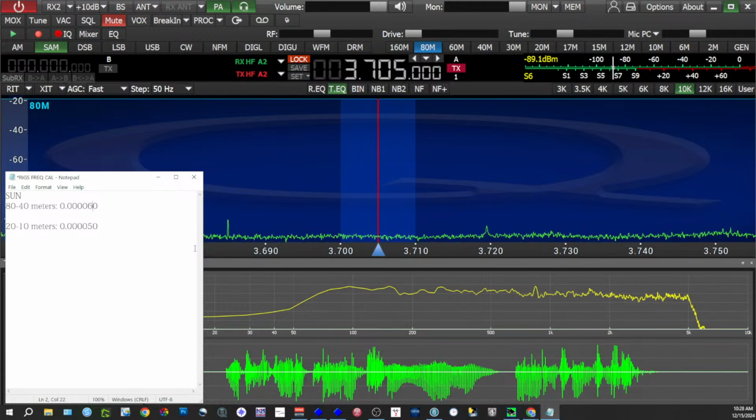The sun, if you calibrate this radio, which most people do, to 15 megahertz, that's the way you do it. Calibrate it to 15 megahertz, put it on there, grab the beacon, and nail it. If you get down to 40 and 80 meters, it's off frequency a little bit. It ain't much, but to the critical ear, it is.